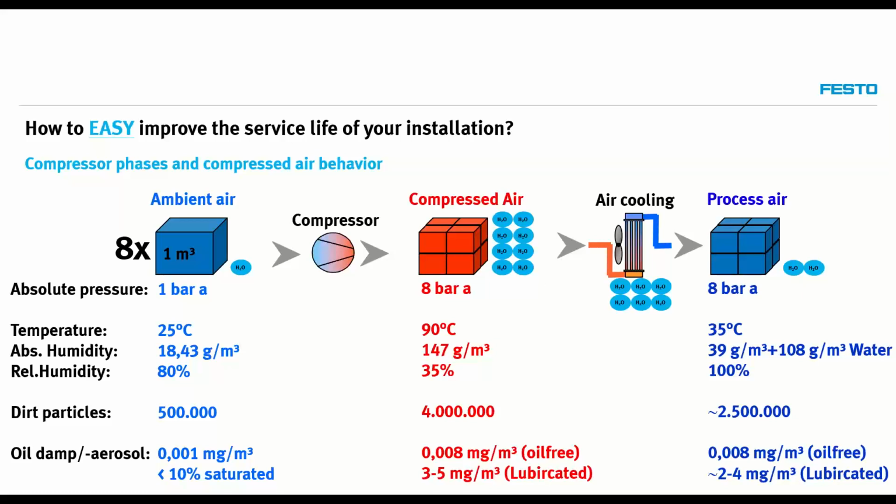In this worst case scenario, you're having a hydraulic system, and this water comes with your pneumatic components. And even in certain cases, it can come to a product. Let's say if you're active in the food industry, this water can touch your product, because there will be a venting of a solenoid valve somewhere in your machine where this water can come out. So that's why we always emphasize and stress the right air quality.